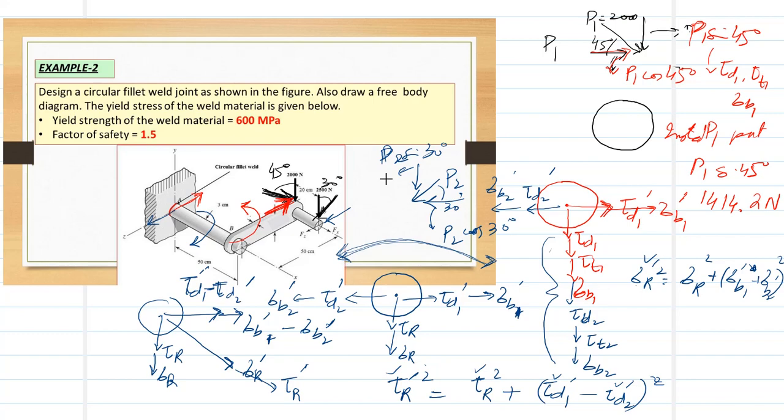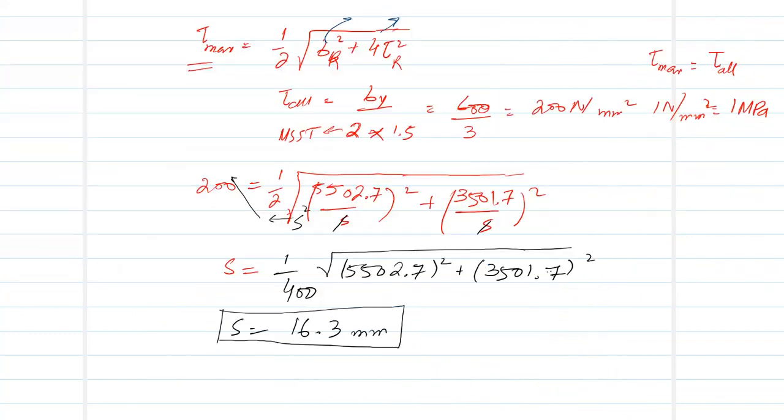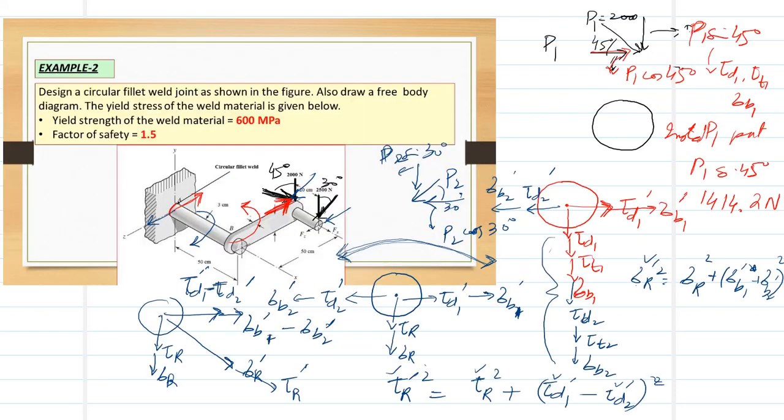And when the stresses are in the same direction, like if this load is also in this direction, there's no problem. These two stresses will directly add up. Just add these two. But if they are acting in opposite directions, and generally you have difficulty finding which one is greater, even if you know from the magnitude, you can easily draw that figure. So if tau d1 is higher than tau d2, just write it. But because the formula contains a square, there is no problem with the negative sign, because the negative sign will dissolve in the square. So that's why we have to solve problems like this.